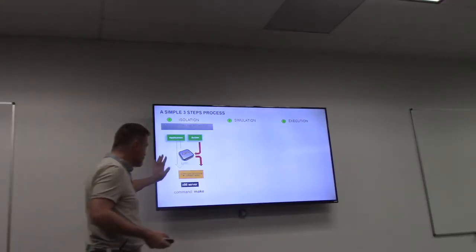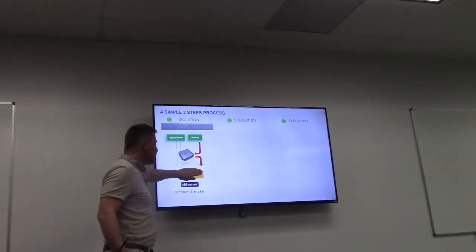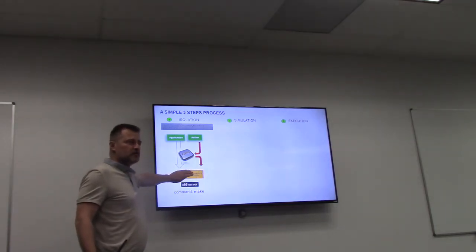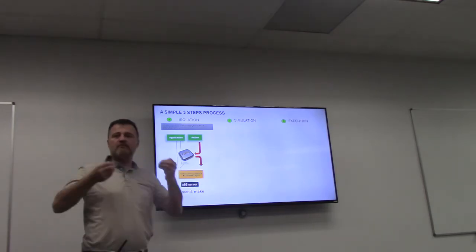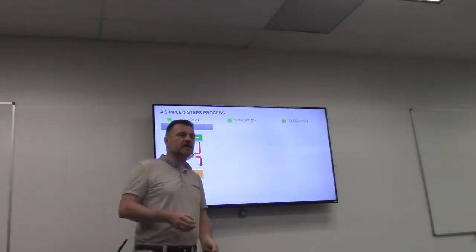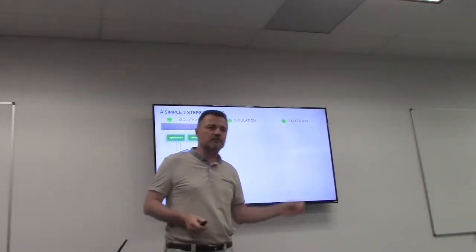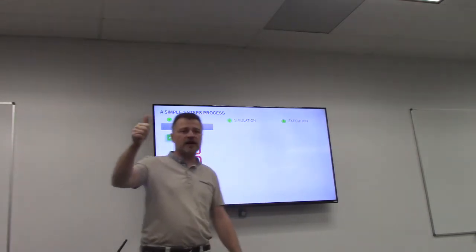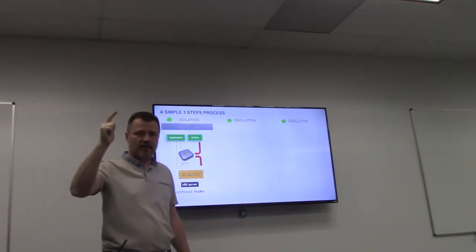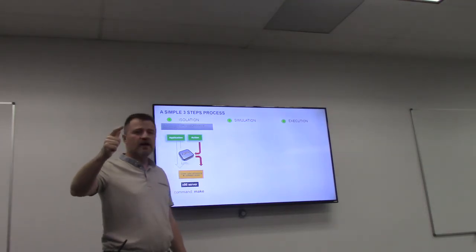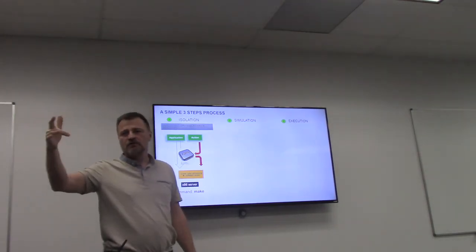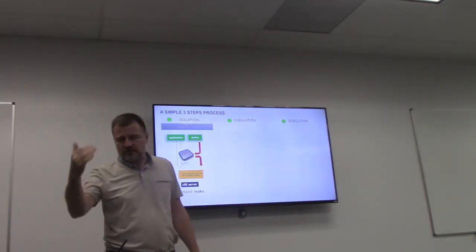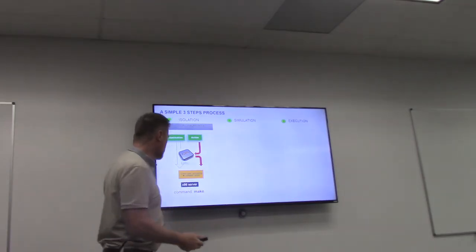The first step we already said: we need to define what is the action that can be externalized, and we need to do some software activity to make sure that we know the boundary of this action. This boundary will be the exact same boundary as the one that we will use for the FPGA. That is, in our case, input register where the data are located, output register where the application expects the return of the data to be located, and a bunch of registers like I want to be polled, I want to be interrupted, any very little, very basic information.